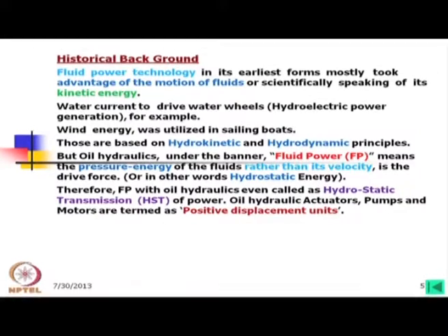Now, here I would like to explain. Let us consider an ordinary hydraulic pump, centrifugal pump. There we are using kinetic energy. When the impeller inside is rotating, then a suction head is generated through which the fluids come in, and that fluid is energized by the velocity and then it is discharged at a pressure which may not be very high, but still we can supply the fluids with certain pressure.